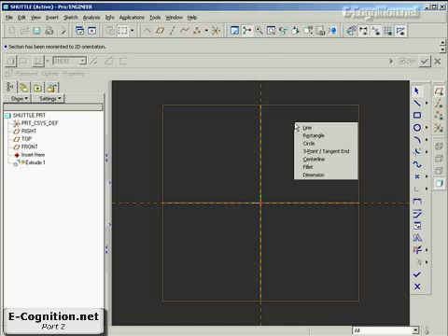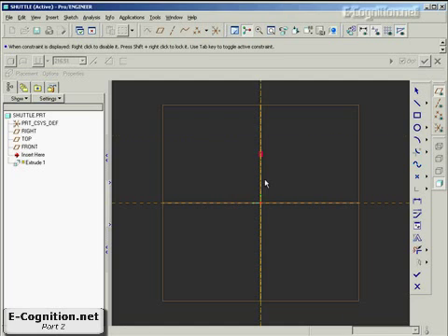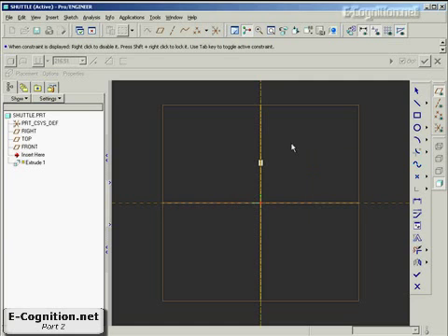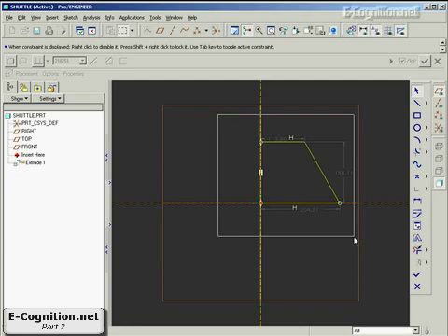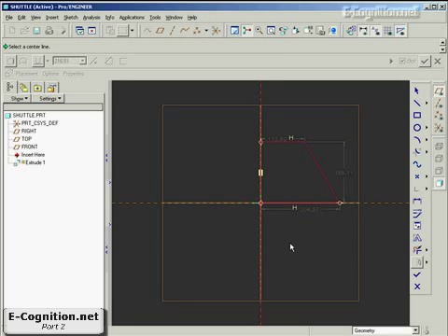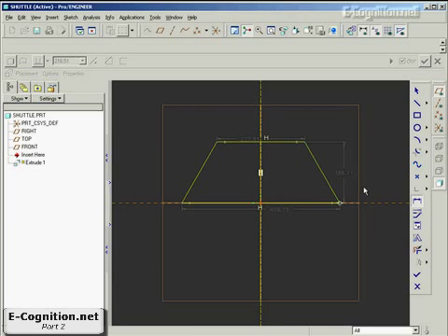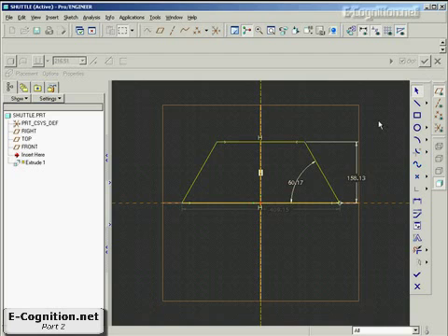And let's drop in a center line. And let's put in a line that goes like that. I'll do only half of it. Grab it all, mirror around the center line, and then add a dimensioning scheme that makes sense. Actually, it's doing pretty good already for me. I just want to put in this angle and this overall height. That should do very nicely for me.